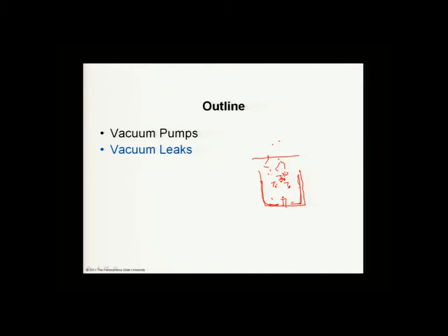Very, very good at ultra-high vacuum pressures, but the chamber has to be brought down into that low pressure regime before you can use this pump. So it's a dead-end kind of pump, as I said, like a cryo pump. Unlike a cryo pump, you don't have to bring it up to room temperature.